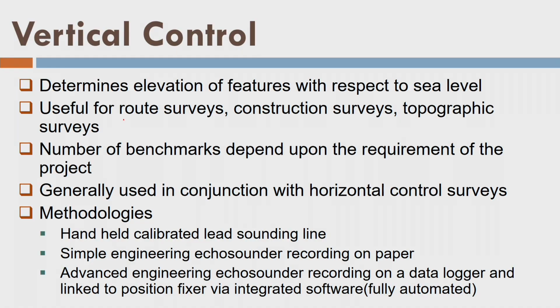Fine. So it is very useful for route surveys, construction surveys, and topographic surveys. So we establish the number of benchmarks depending upon the requirement of the project. It is always in conjunction with the horizontal survey. We do not separate the horizontal and vertical survey here, right?